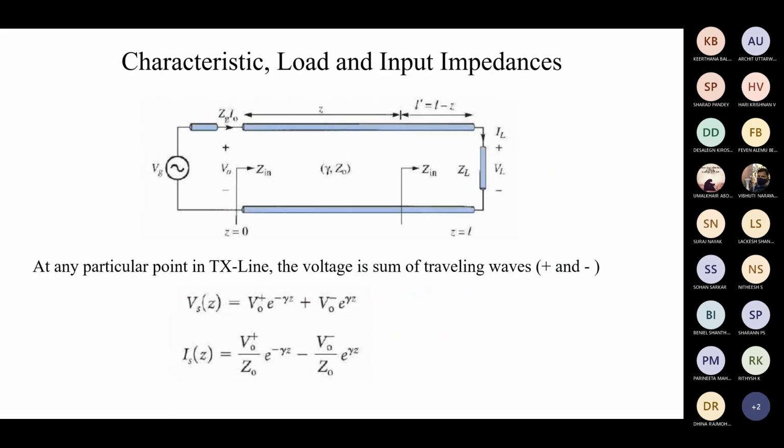Now for a transmission line, we have to calculate these impedances. Okay, so in order to do that, we are supposed to make a clear statement that we have a source and a load, and both are connected by a transmission line of length L. In order to define the transmission line, you should always be very clear, and in fact you should be professional enough to define properly whenever you are drawing the transmission line, that you have to mention alpha, beta, and the Z0 value.